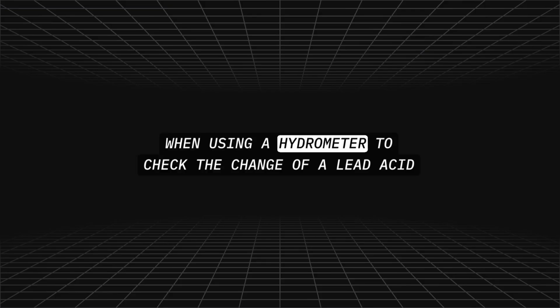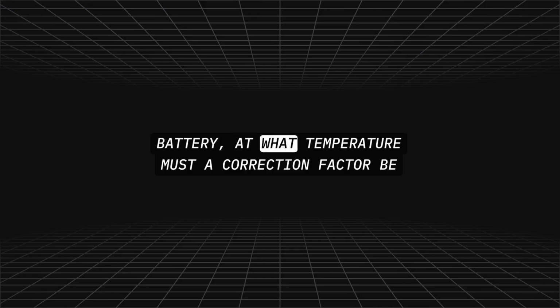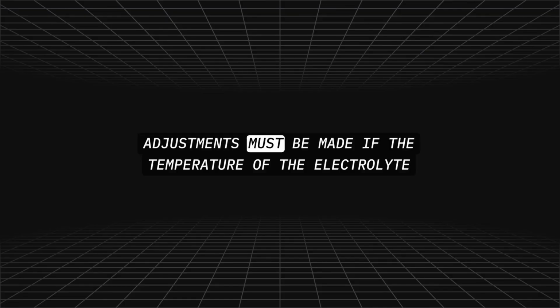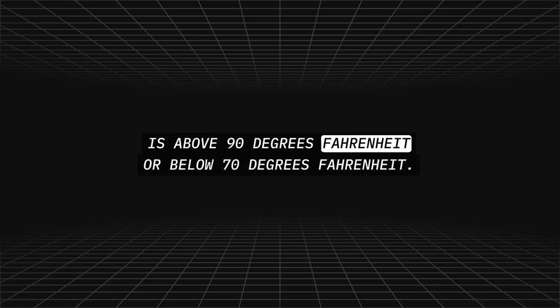When using a hydrometer to check the charge of a lead-acid battery, at what temperature must a correction factor be applied to the reading? Adjustments must be made if the temperature of the electrolyte is above 90 degrees Fahrenheit or below 70 degrees Fahrenheit.